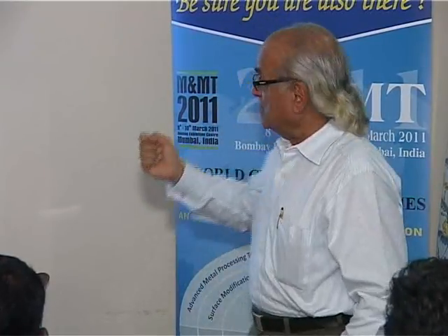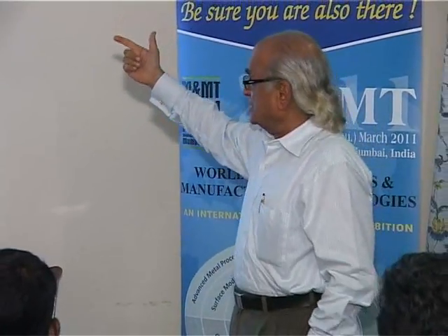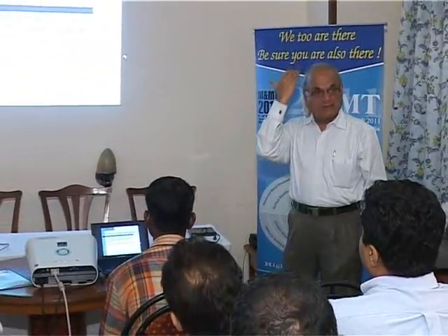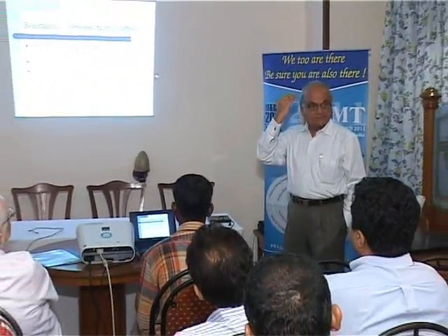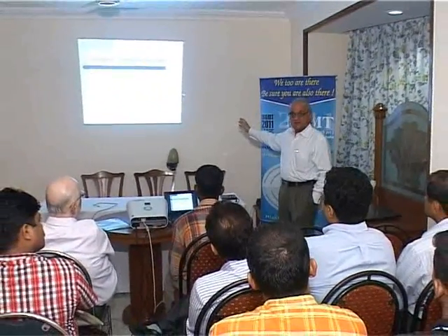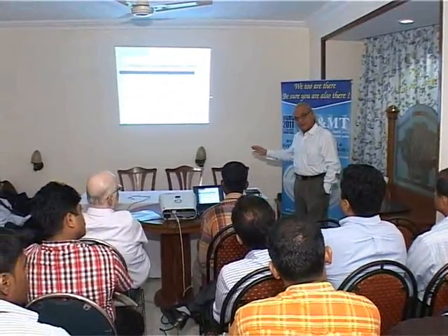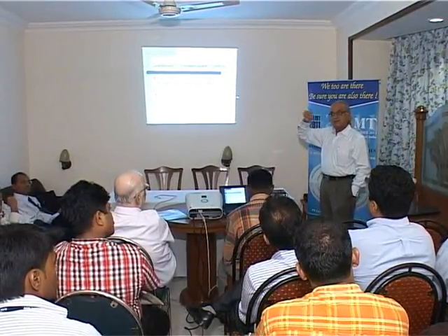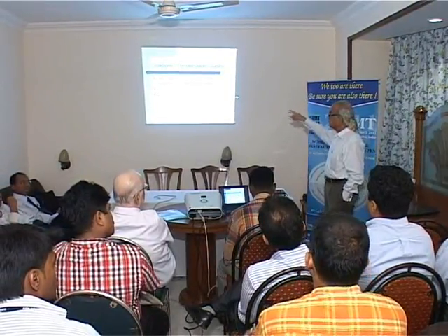And therefore, MI thermocouples, mineral insulated thermocouples, this guy makes a lot of them. And you tie these thermocouples to the jobs and let the thermocouple travel along with the job. 30, 40, 50 meter long thermocouples, you tie to the job and let it go there, and the entire profile of the temperature in the furnace can be mapped. That's why it is called mapping.